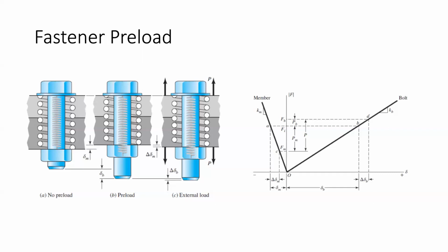So torque is the most common way of detecting how much axial load you have in a fastener, but it can actually be somewhat imprecise. A lot of torque wrenches that you use are plus or minus 25%, which is kind of an absurd number, right? You have this really sensitive joint and the variance you have is plus or minus 25%. It's kind of crazy, but there's strategies that people use to assess the failures of these systems where you lose this preload.